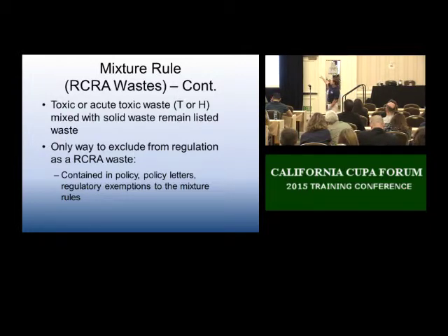And when we talk about the waste extraction test, once again, it's 2 tests. How much of that chemical is in the waste? Is it at or above that concentration? It's a hazardous waste in California. Federally, it's a dilution process. So California says, I kind of like that idea. So we're going to have a similar test method to the federal criteria. But in California, if you've got lead in your dirt, when you send that sample to a lab, what they're going to do is they're going to say, well, yeah, let's figure out how much of the lead's going to move out of the dirt. So let's dissolve it, and they're going to use citric acid. The federal government uses acetic acid. So it's similar, not the same.